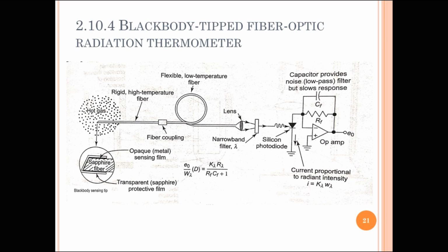The probe temperature rapidly approaches the gas temperature, but just as in other probes, of course, conductive and radiative heat losses prevent the sensing film from exactly reaching the gas temperature. However, the present probe exhibits significant advantages since the conductivity of the sapphire is 14 times smaller than that of typical thermocouple metals, and the fiber's optical transparency allows the cavity to project radiation characteristic of that temperature along the sapphire fiber toward a silicon photodiode or photomultiplier